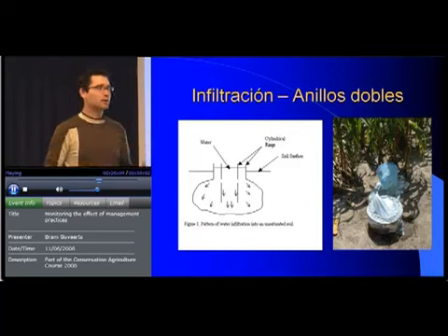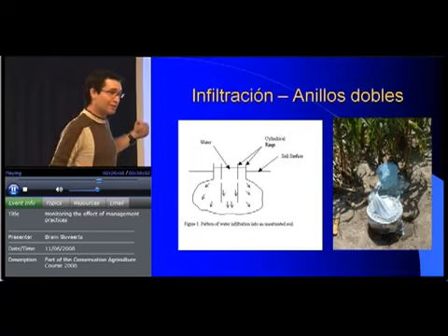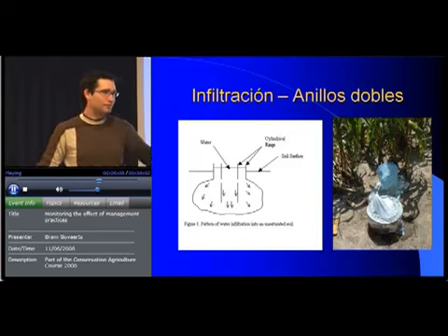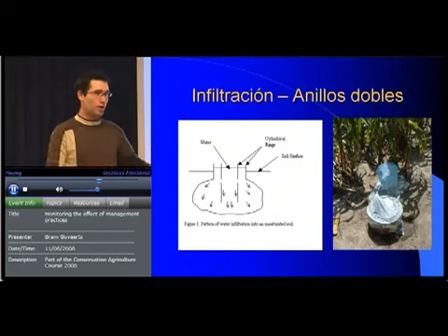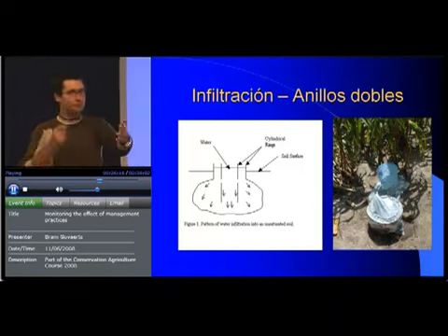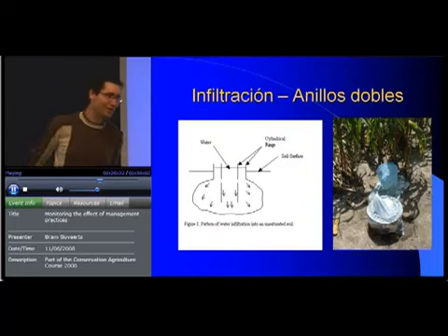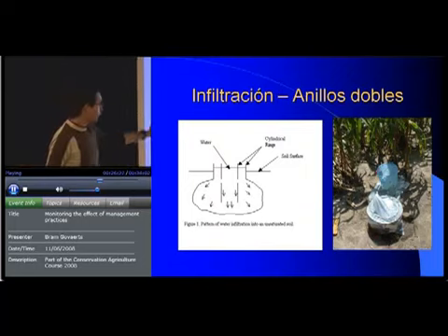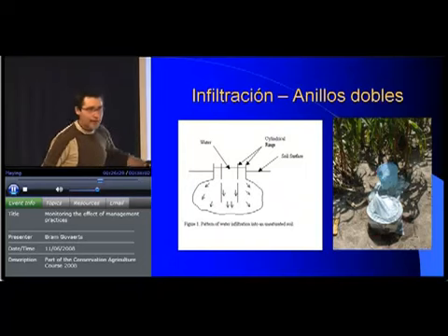But in both circumstances, what happens is the soil crust just breaks open, right? You have never moved the soil, but when you put the double rings in there, all of a sudden the soil breaks open. So then you imagine you put water on that, it is going to go in very, very quick, right? So the double rings are okay, but they are difficult to use